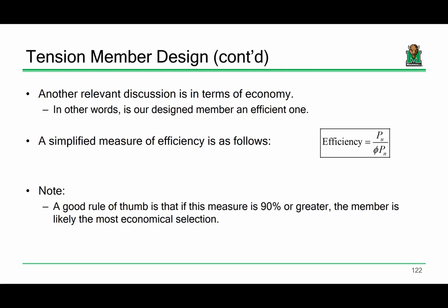Yes? That's a good question. First off, it is like The Price is Right, you know, closest to 100% without going over, right? At least somebody got the reference. Now, as for whether or not is there a too close? Well, mathematically, I'd say no. I mean, if it's 99%, go with it. Now, a lot of practicing engineers would back it off a little bit, just in case a member gets dinged up during shipping or something like that.